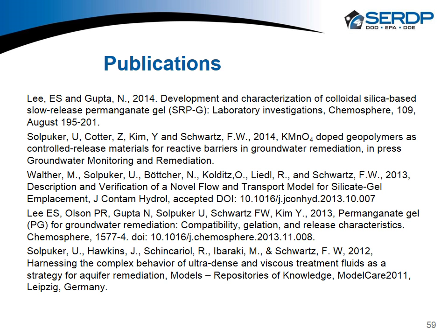I think in our case, the viscosity of the sodium silicate compound, when it's mixed with potassium permanganate, so the potassium permanganate is dissolved, everything is in a solution when we put it in there. The viscosity is perhaps 3 times the viscosity of water, so it's extremely watery. It's injectable, and then after it's injected, it takes upwards of 20 minutes perhaps to become a gel. We think there are ways to lengthen that.